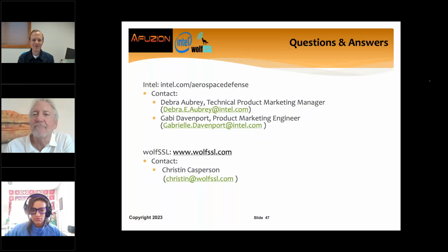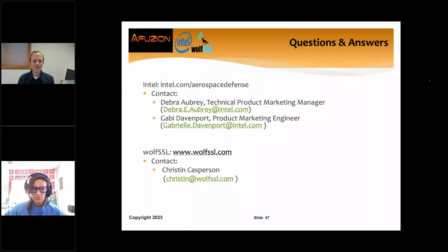So, as you noticed already, the HAL is an abstraction layer for porting to different platforms. We do already support several architectures, and within that same architecture, it usually boils down to just providing access to non-volatile memories that store the images that have to be verified. Of course, porting to a new platform outside the architectures that we support takes a little bit more effort from our side, but I think we support about 7 or 8 different architectures besides Intel 64 and 32-bit, and of course most of the most common ones on the market.